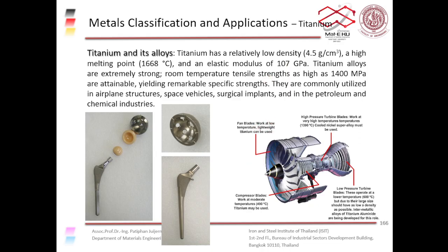Titanium alloys. Titanium alloys have been around for a while now, and have been used quite a lot because they have really high strength comparable to steel. Aluminum alloys and magnesium alloys, you can increase the strength by alloying or precipitation strengthening, but the strength is not comparable to steel, right? But they have much lower density, so you can probably increase the thickness of the section so that the overall strength can be comparable to that of steel.